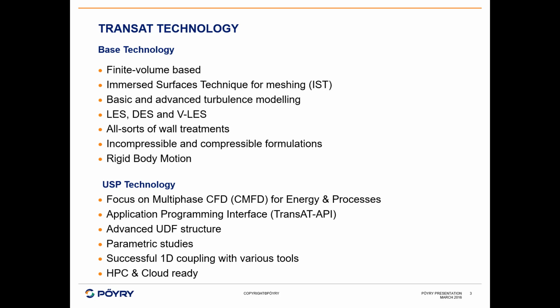the UDF structure, or user-defined functions, where through C++ programming, users can add or modify the solver, models, and post-processing of TransAT. Parametric studies makes it possible to automatically set up and run a parameterization. And TransAT has been coupled with various tools such as 1D solvers like Olga. TransAT is key for high-performance computing and is accessible through cloud services.